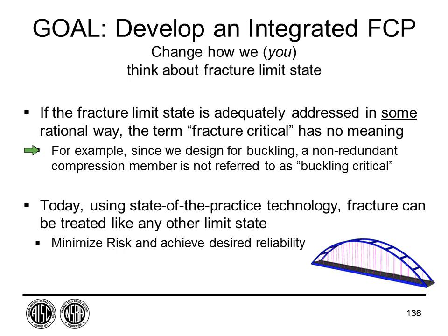If you lose a compression member in a truss, that's very bad. But we don't do anything special in inspection for the life of the structure. And that's because we did a lot of research and design and testing, and we can now be confident buckling is no more likely to happen than any other strength limit state. Today we can do the same for the fracture limit state.